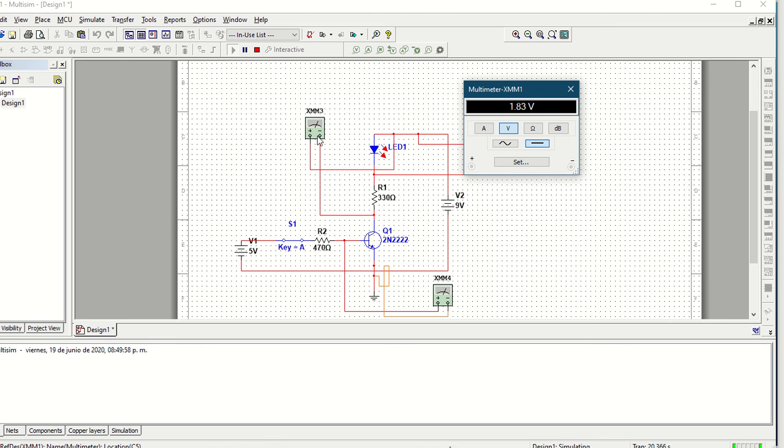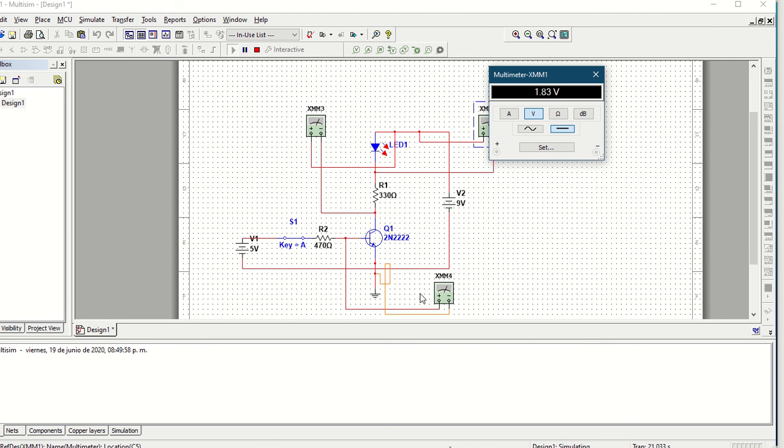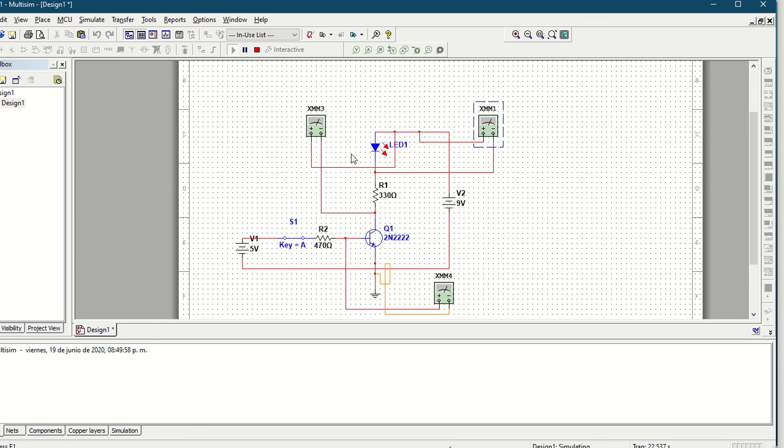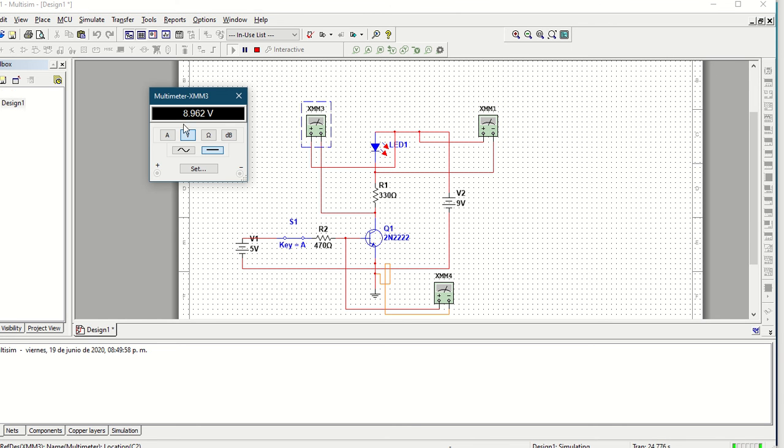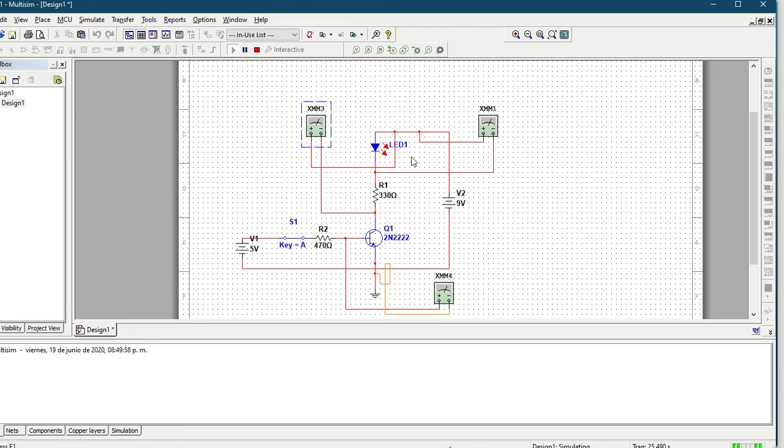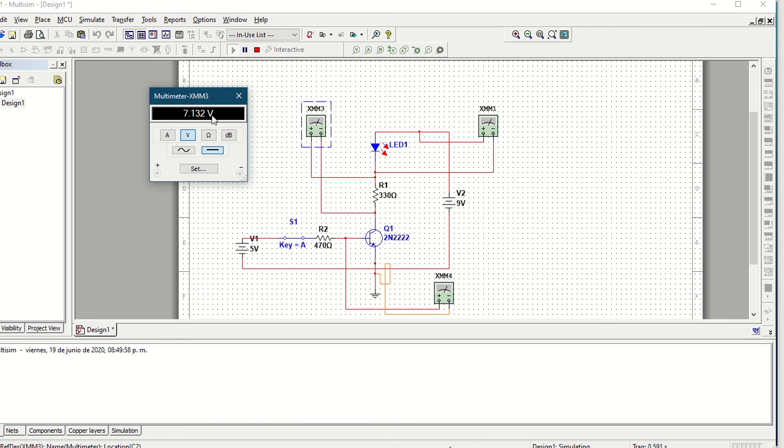Let's take a look at the voltage across the resistor. There must be a drop of voltage because of this LED. Here we have the voltage drop. Oh, let's stop, this is not right. To take a look at the voltage drop, here, 7, because it's a 2 volt LED. So 9 minus the 2 volts, we have 7 volts.